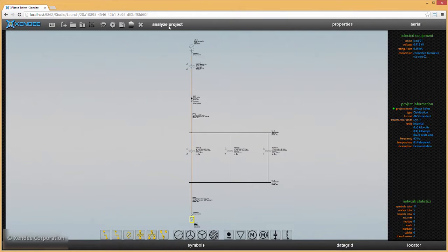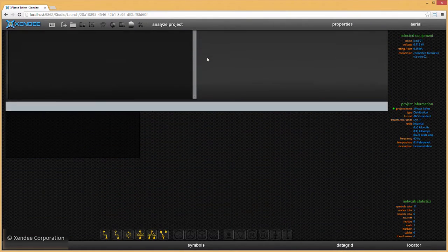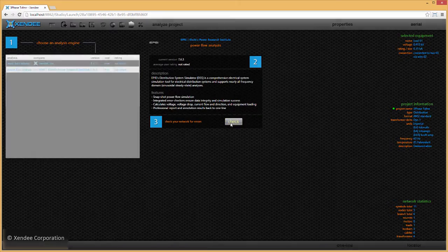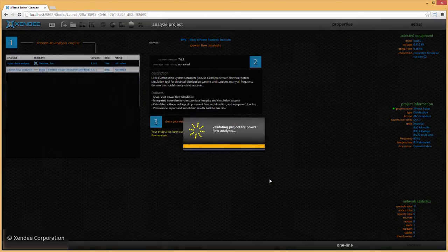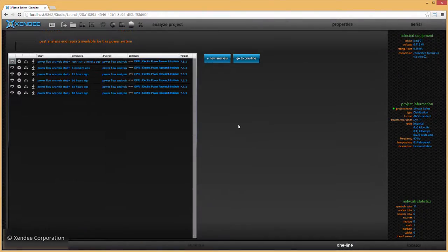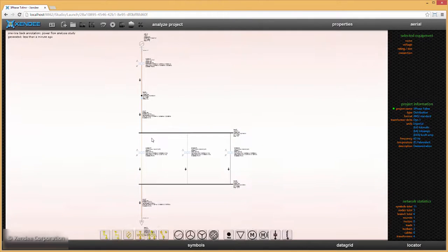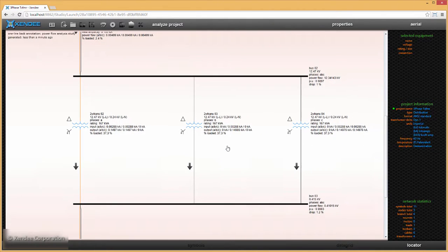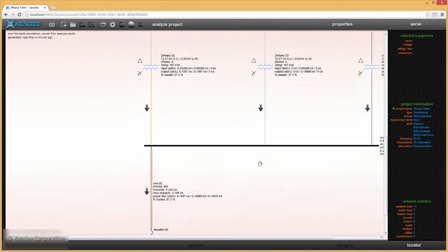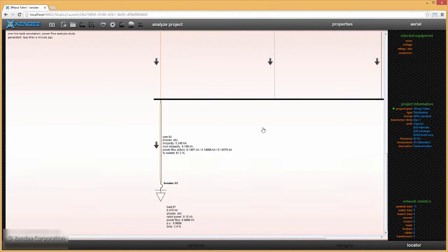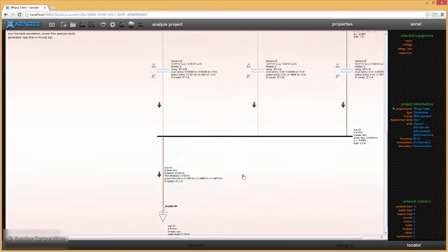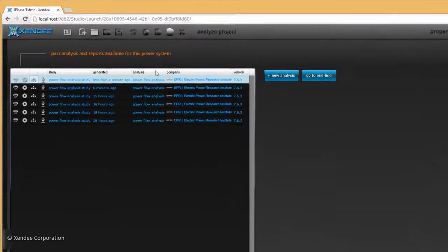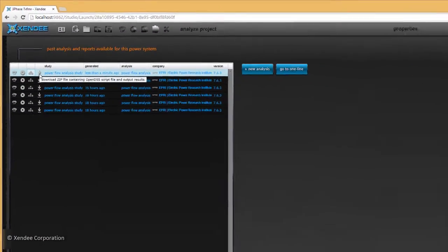We will perform a power flow simulation via EPRI OpenDSS, and you will note from the back annotated simulation results that the voltage angle is not an option that can be viewed on the one-line diagram. This has been done to keep the user interface decluttered. However, detailed output results are available in Excel output files. And these are created with each simulation, and they can be downloaded to your PC for detailed investigation of the results. I'll go ahead and download and save the zipped output results for this simulation as dyn1.zip.